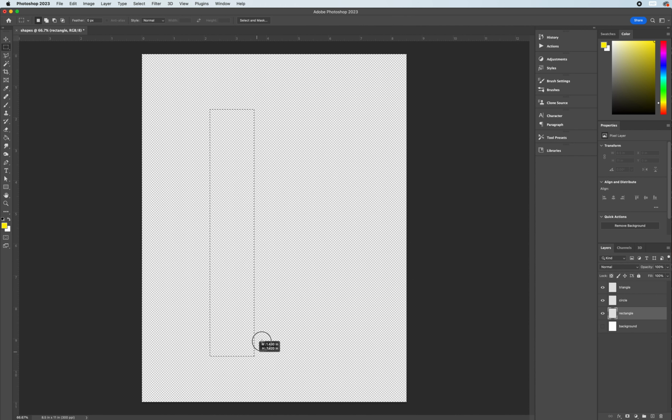We want to have a tall rectangle, a wide rectangle, just a matter of moving your cursor around so you're satisfied with the shape. If you are looking for a perfect square, we can always hold down Shift on our keyboard. If I click and drag holding Shift, you get to see that it will maintain this perfect square.